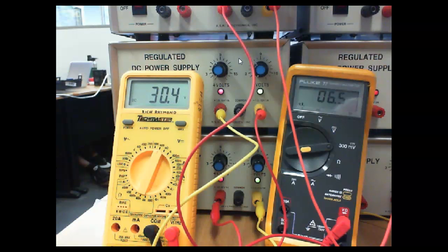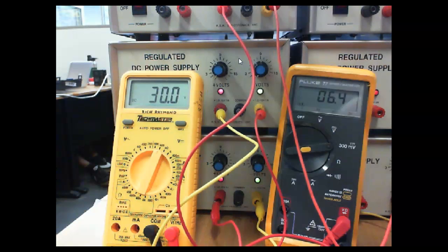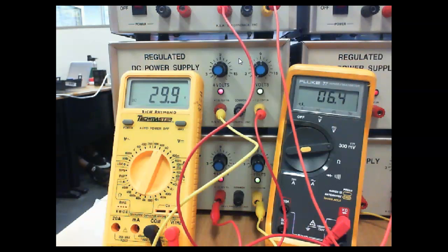So that's one of your measurements. So y'all need to go ahead and write the voltage drop across the diode down. Across the resistor. So that's the voltage drop across the 1 meg, and then we can use that to calculate our current. So we're going to do 30, and then we're going to go up to 60, but we're going to do it real slow so y'all can see when it breaks over. Or not real slow, we're going to do it slow.